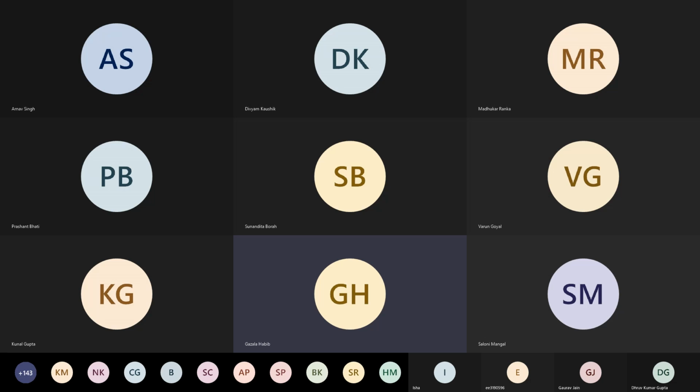Then Fb, the force due to buoyancy, can be given by again mass multiplied by G. That is the mass of water replaced, which is the particle's volume multiplied by rho W, because this is the water which will be replaced by the particle, and it gives the buoyancy force on the particle, into G. So this will become pi by 6 into dp cube, multiplied by rho W into G.